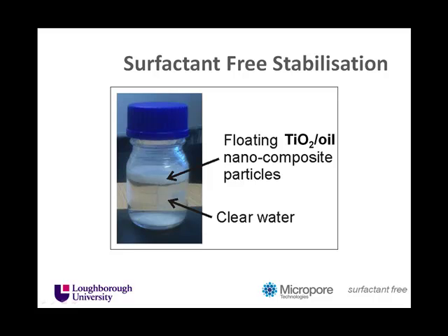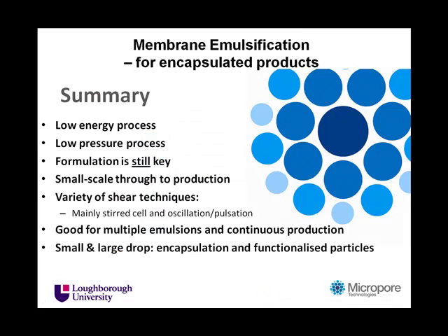So membrane emulsification. For encapsulated products in particular, what are its advantages? Well, it's a very low energy process using the style of membranes that I've just discussed. One of the reasons behind that is it's a low pressure process. We are really using sieves rather than depth microfilters.